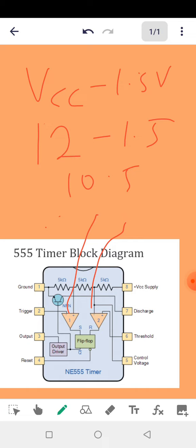Now, it's not like this is what you get every time, because at times the voltage may not even be up to minus 1.5. It may be minus 1.4, it may be minus 1.3, it may be minus 1.35. It depends. Now the worst you can get should be VCC minus 2 volts, depending on the current you draw and the temperature you are working with.